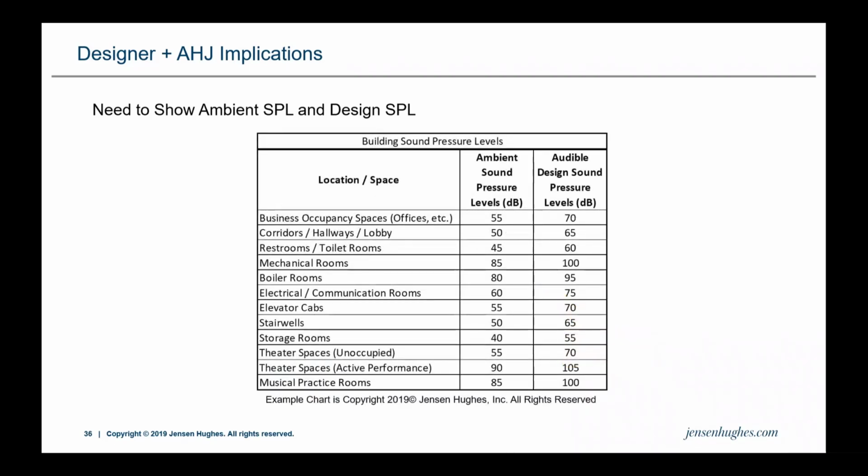This might be a better approach. A chart like this may provide more flexibility in the design of individual acoustically distinguishable spaces, and it also allows a better testing approach to the various spaces. Think of the theater space we were looking at in our earlier example. In an unoccupied time, it's a very quiet space, and we don't have any ambient sound level to speak of to overcome.